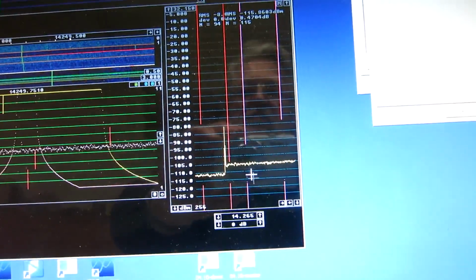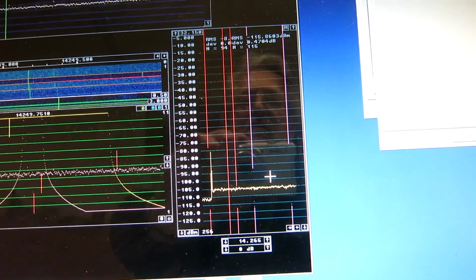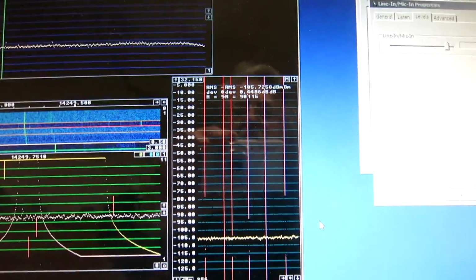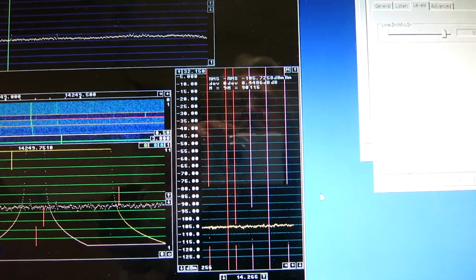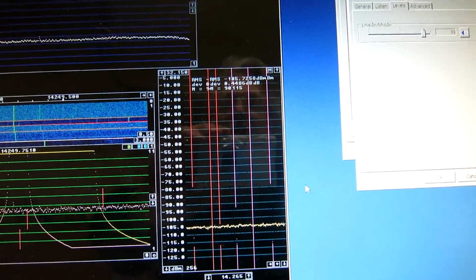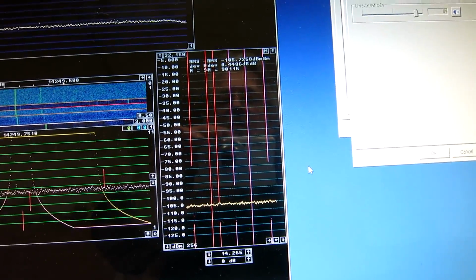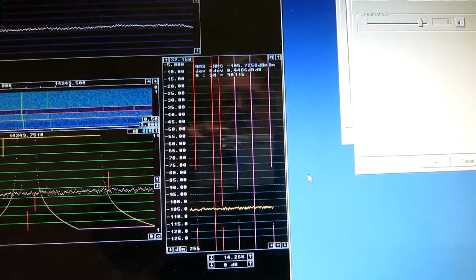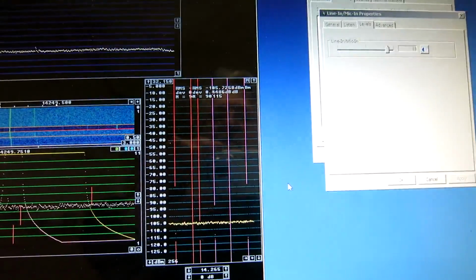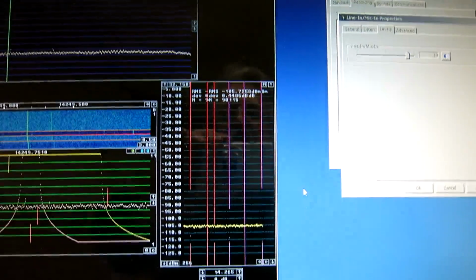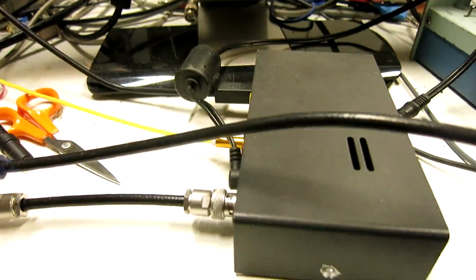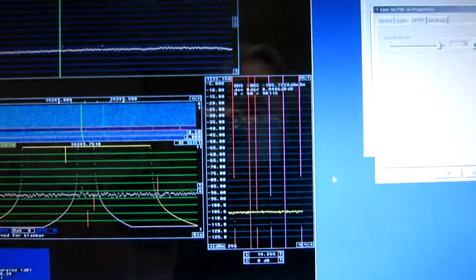Anyway, here the noise floor is minus 105, and that will be the value I report in the chart over sound cards, because it is likely that we have strong signals 100 kilohertz away from the signal of interest when using the Softrock, and those are not much attenuated by the op-amp filters, but they are attenuated in this box, as is normal for a Softrock.